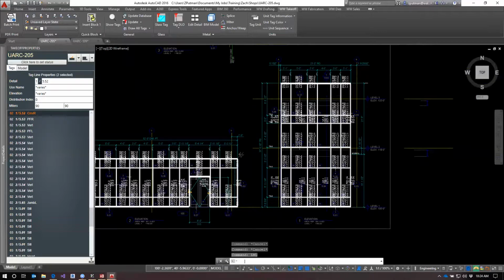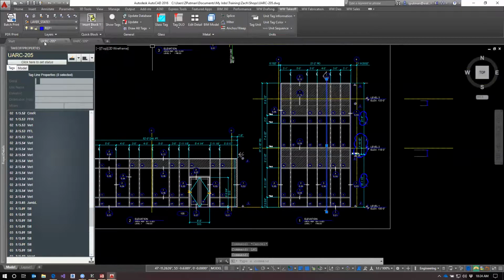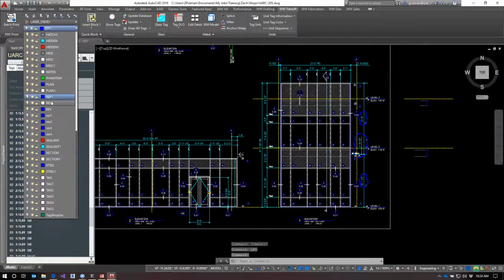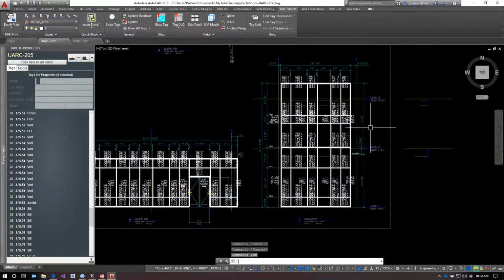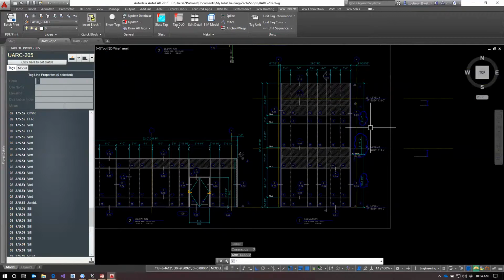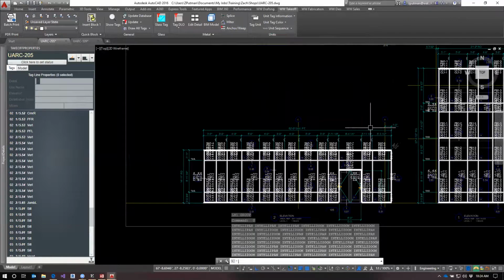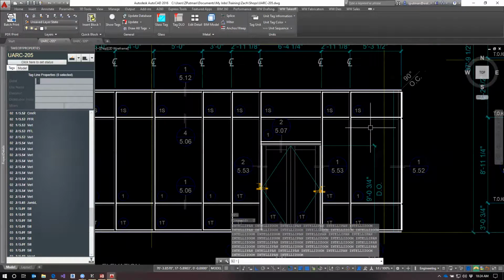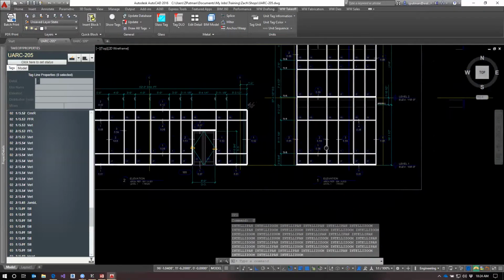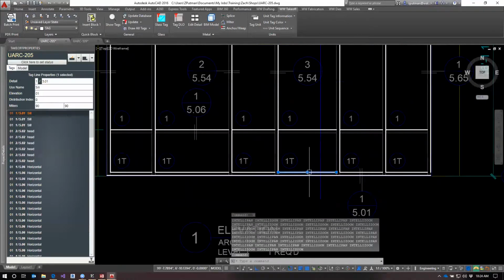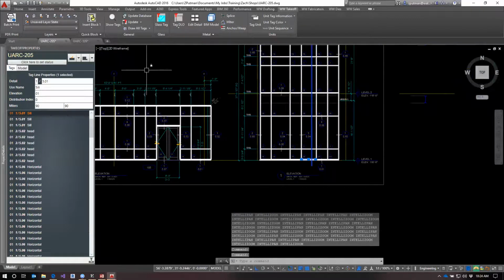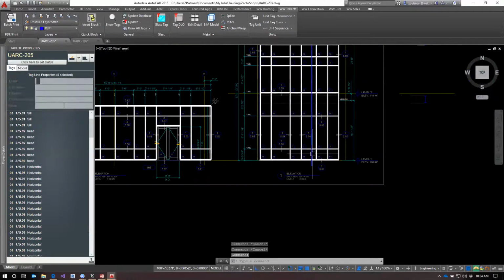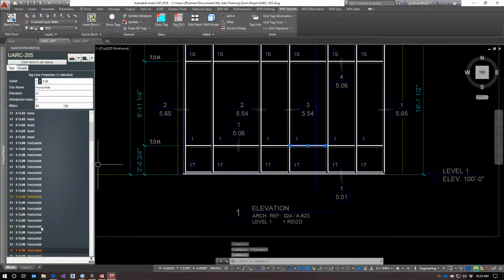So I'm going to go into the drafting layer and just swap this out for the Rep 2 layer. So it'll be white. Actually, let me undo. Just undo back. Now, when you undo, you're only undoing the stuff that happened to this drawing, right? You're not undoing anything that happened to the database. So just hitting undo won't undo your UPD, but it's a convenient way to go backwards and prevent these taglines from switching their detail number.